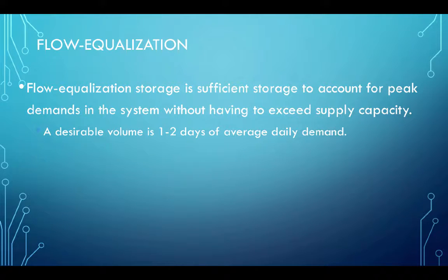Flow equalization, or what's called service storage, is sufficient storage to account for peak demands in the system without having to exceed supply capacity. A desirable volume, for lack of any other ways of measuring it, would be about 1 to 2 days of average daily demand.